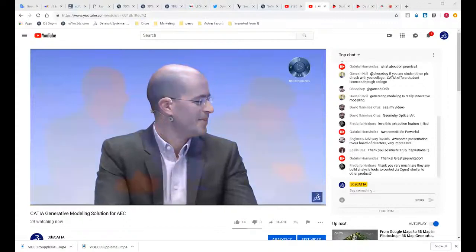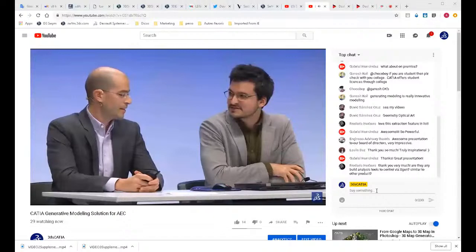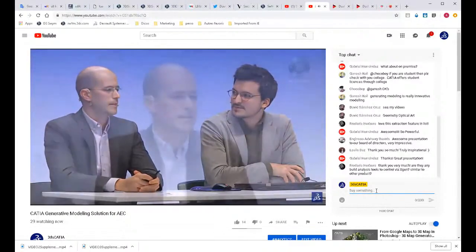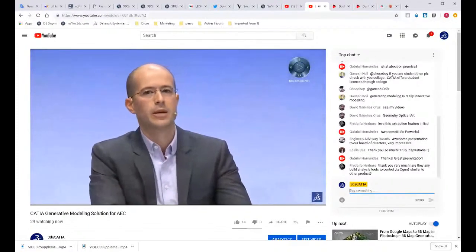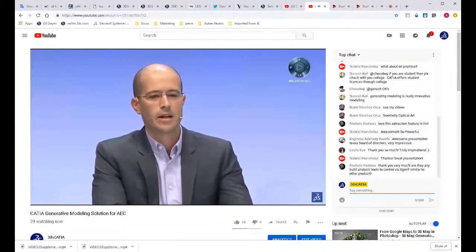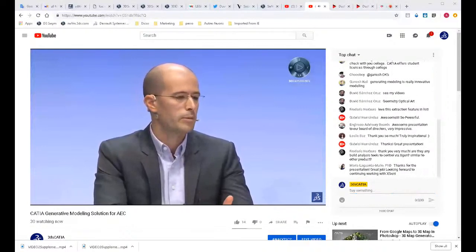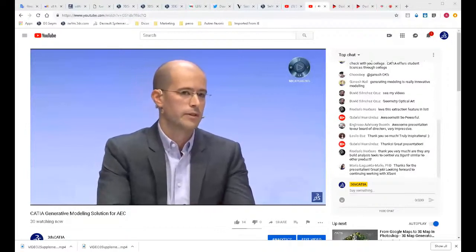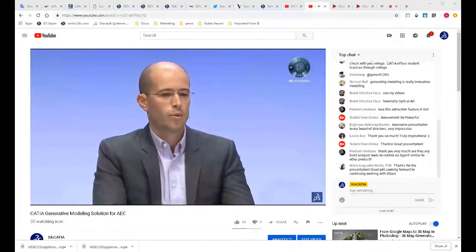Thanks. Third one, can I use X Generative Design to create and modify assemblies? That's another great question. Today, no, you cannot use X Generative Design at the assembly level. However, you can reference parameters and geometry across assemblies using traditional CATIA mechanisms. So you saw in one of the videos how we reference global parameters to drive multiple X Generative Design models across an assembly, and that's where it stands today.